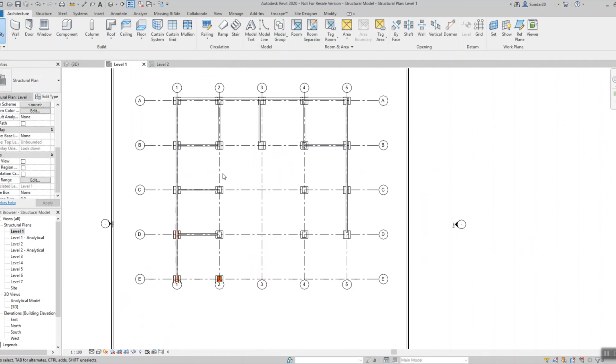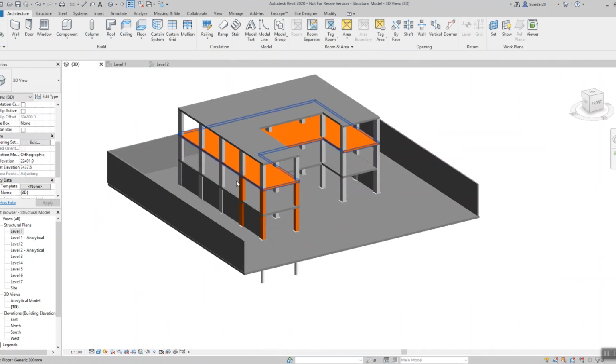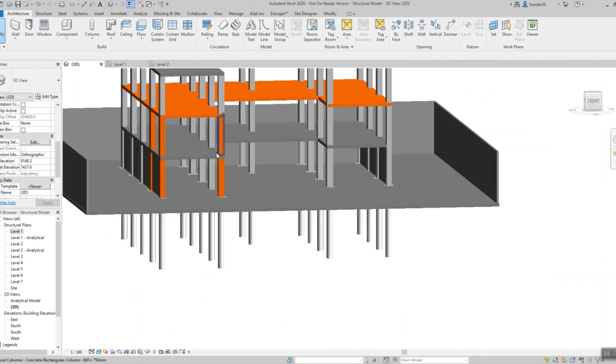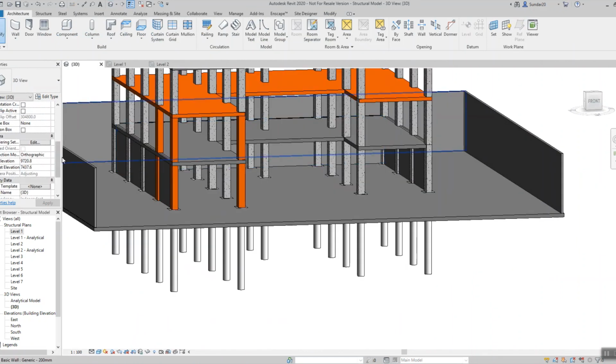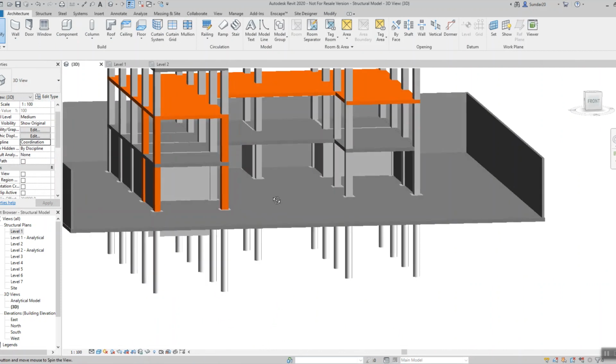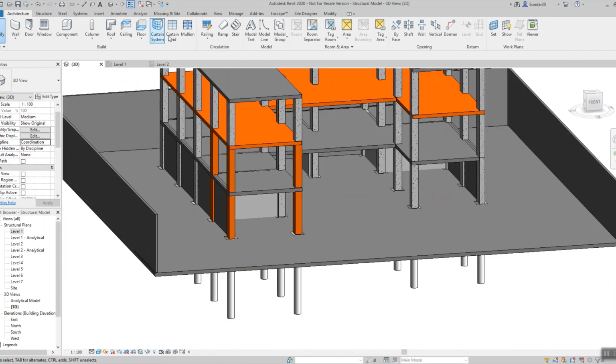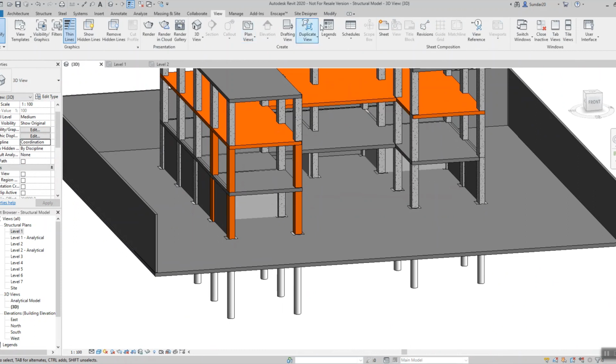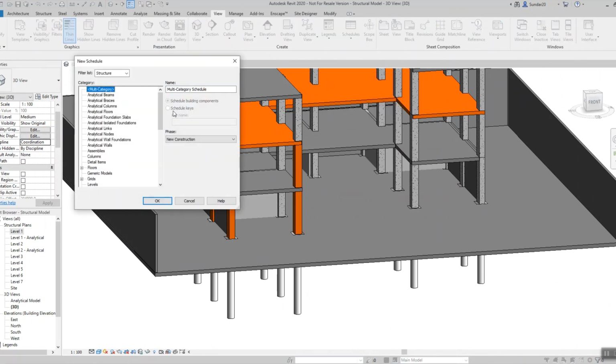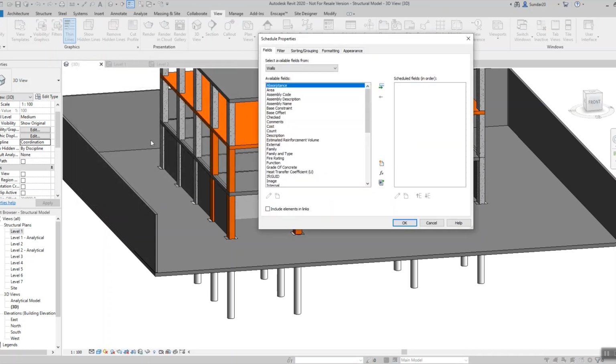Now in the differentiations, if I want to add, again, here there is a discipline restriction. So let me set it to this. See, all the walls are visible. So now if I want to differentiate, I'm doing it very simply. Go to walls. So in walls, I'm just choosing. By default, you need area and type, all these things.